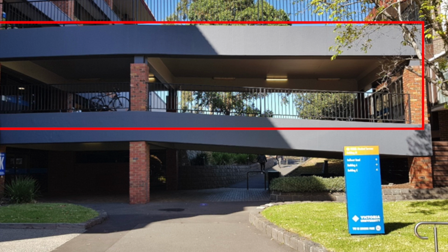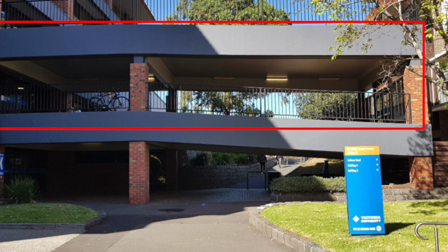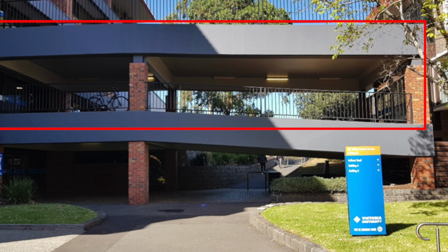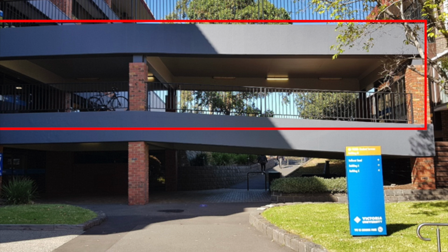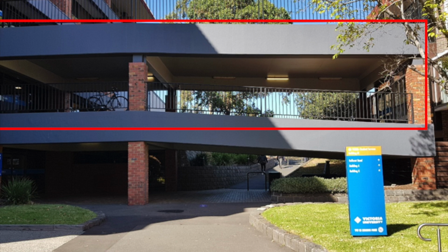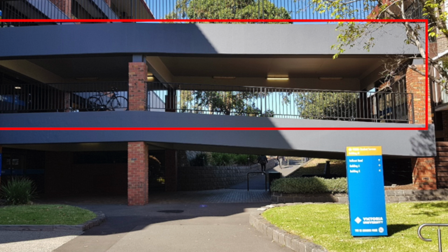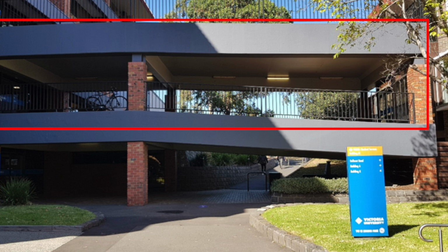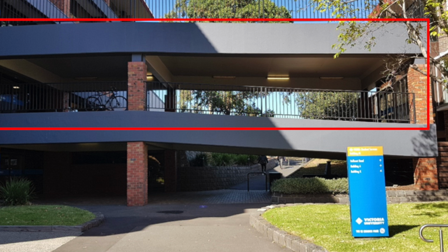The last section we calculated is the rails. The rails have a density of 7,700 kilograms per meter cubed, which resulted in a volume of 1.347 meters cubed and a mass of 10,356.5 kilograms. As we added all these up, the total mass of our bridge is 145,759.7 kilograms.